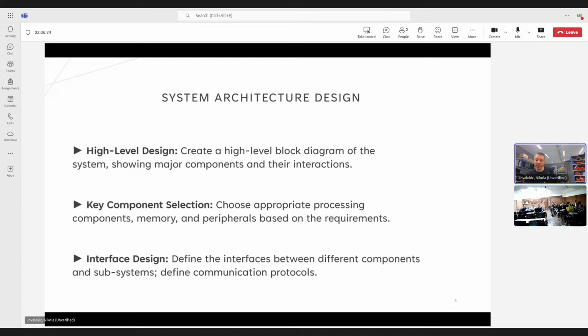If we talk about ML applications, we will also need the high speed interfaces as well. We mentioned some of the high speed interfaces. But do you know what is the major problem of high speed interfaces in terms of interference in the system? I think the first thing that comes to my mind is distance. It depends on the application. If you want to connect a ton of sensors and they are spread out over some distance, you automatically need to rule out the fastest IOs. That's the first thing that comes to mind.